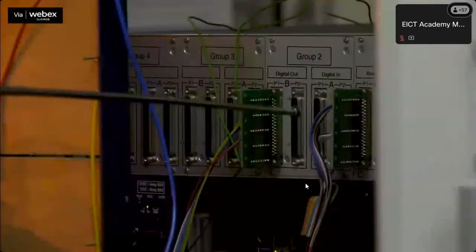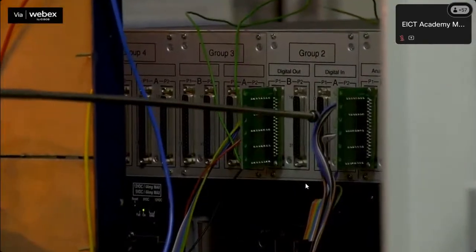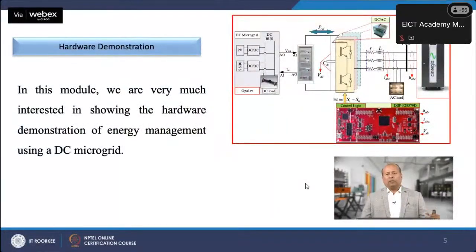To emulate the DC bus voltage through the power amplifier, the DC bus voltage is sent out through the analog out of the OPLRT by scaling down to a 0 to 10 V level, which is the power amplifier analog input voltage level. The power amplifier is configured to external mode, which gives the voltage corresponding to the analog input voltage value.